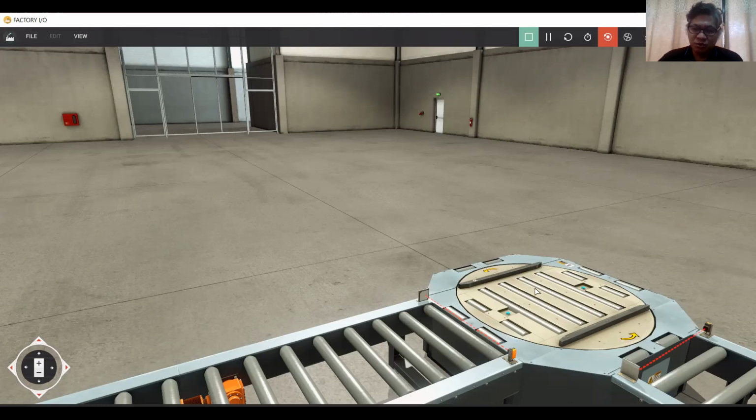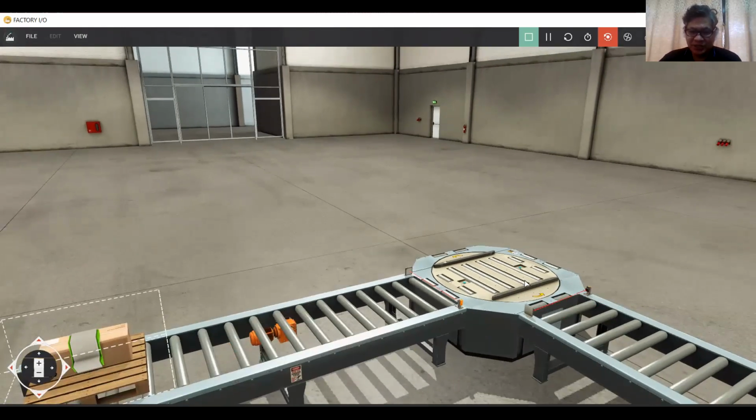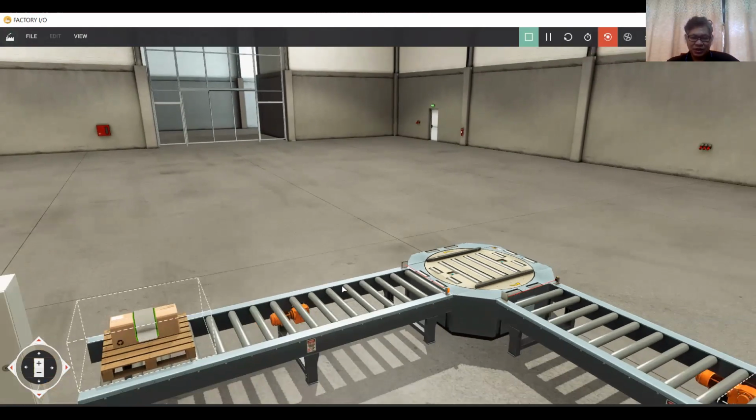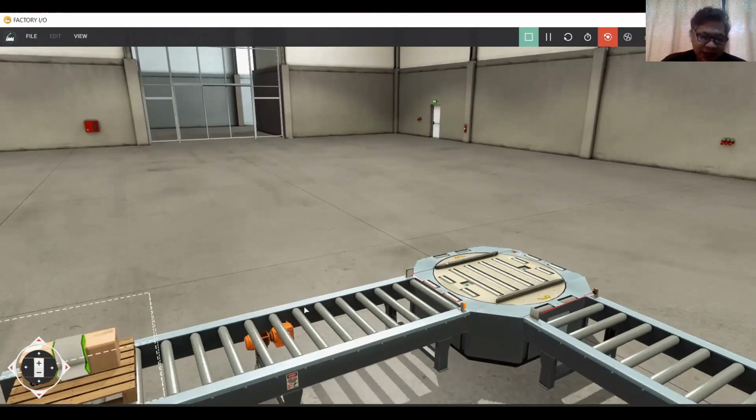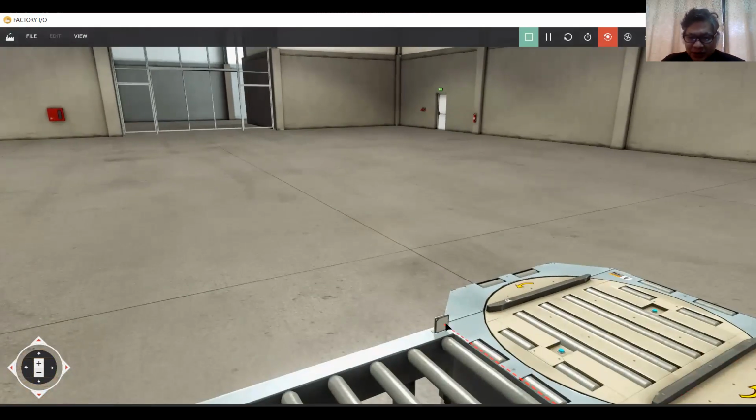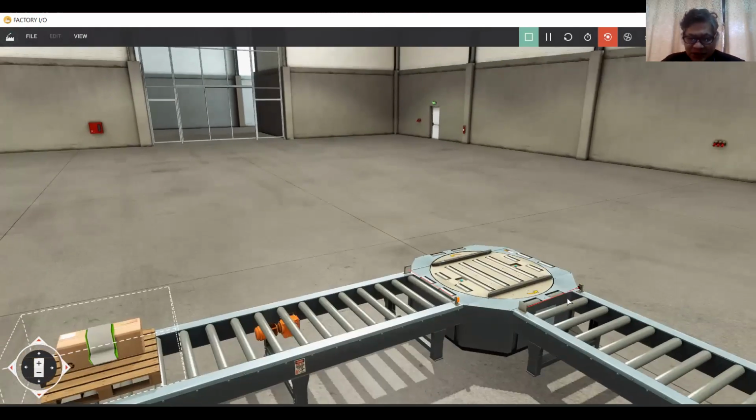So you have two motors in this transfer area. The motor transfers from conveyor 1 to this transfer table, then you rotate it. You have a device to rotate it, probably a motor with gearbox, or pneumatics is possible, but this is a motor with gearbox. So I can reverse it and I forward it. All in all, you have 4 motors, and I have an entry sensor here, and an exit sensor here.